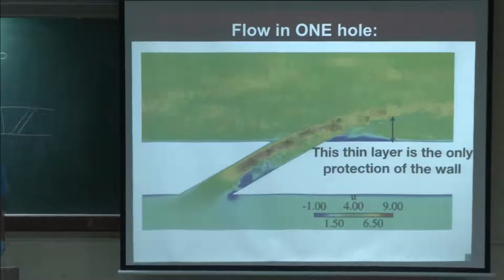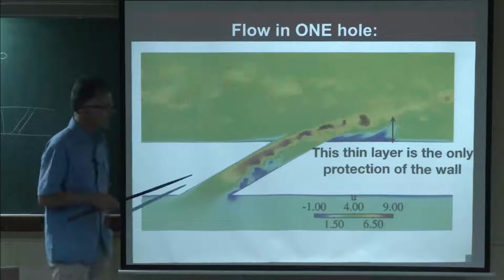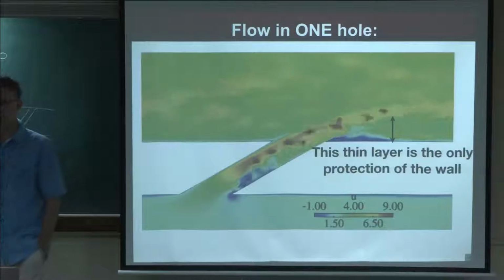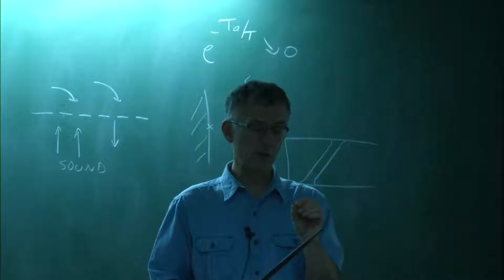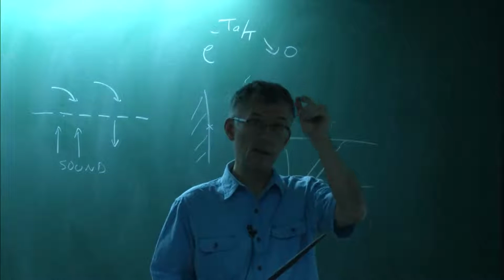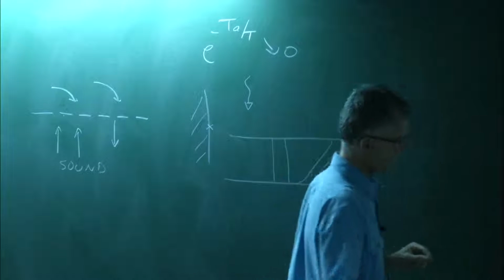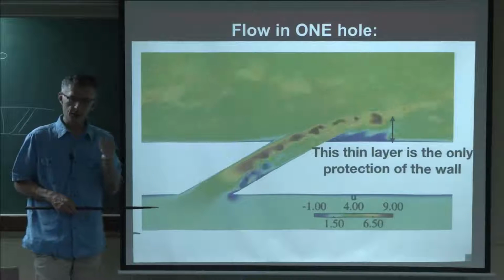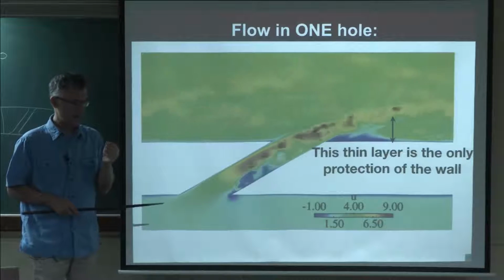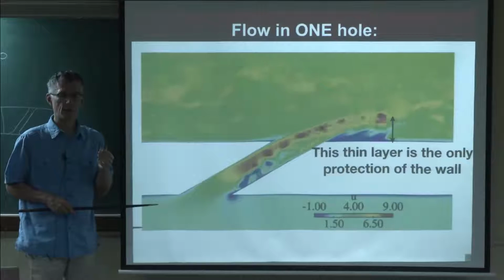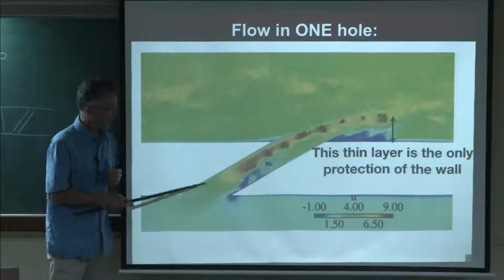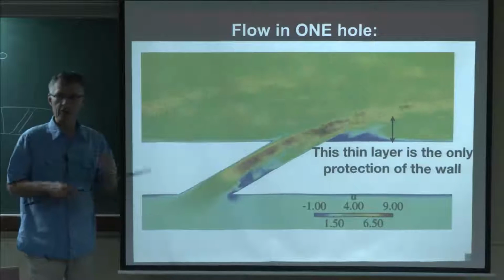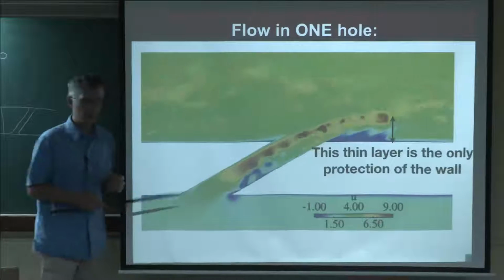One of them, which is famous now, is if you fly in the cloud of a volcano. The particles produced by the volcano are solid in the atmosphere, but when they go through the compressor, they melt and become like droplets. These droplets splash here, and when they splash, they become solid and stick here, so they just block the hole.